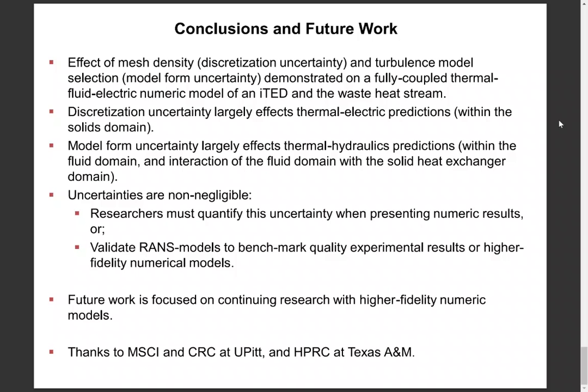Due to the interplay between the solid and fluid domains, it is recommended researchers quantify this uncertainty when using numeric models. Due to the large uncertainty arising from the selection of turbulence models, the RANS-based models must be validated to either benchmark quality experimental data or against higher fidelity numeric models before definitive performance predictions can be made.